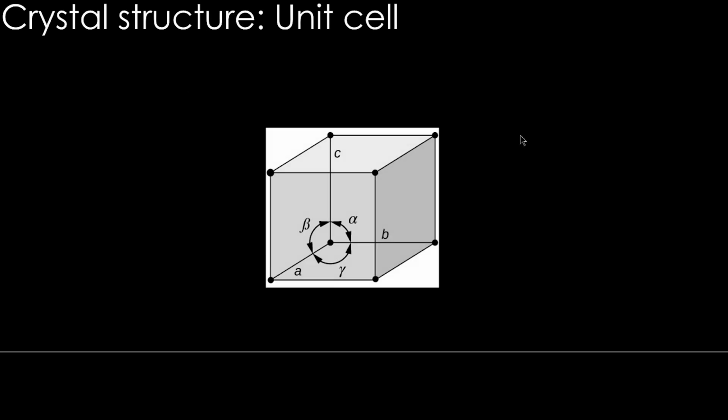Right, let us come back to the unit cell that we saw, because most of the materials that we will be dealing with are crystalline in nature. This particular unit cell is at the heart of it. A unit cell has these different lengths A, B, C, and alpha, beta, gamma, which are the angles between A, B, C. These 6 things together, A, B, C, alpha, beta and gamma, are called lattice parameters.